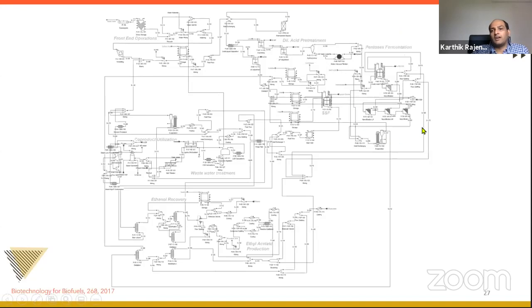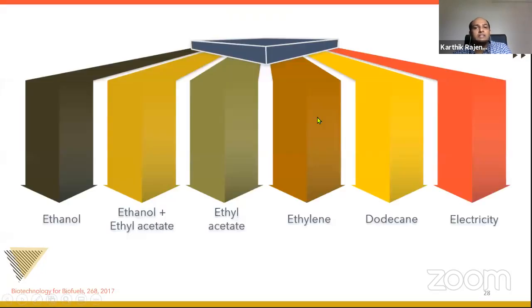Pentoses go for a 5-sugar fermentation to produce acids, whereas the 6-sugar fraction goes for the SSF process to produce ethanol. Then they go to the upgrading system for ethanol recovery. Similarly, the byproducts go into co-product utilization for electricity generation and wastewater treatment and reuse. So we have simulated more than 100 unit operations in this picture, and similarly, we have tried out different cases.